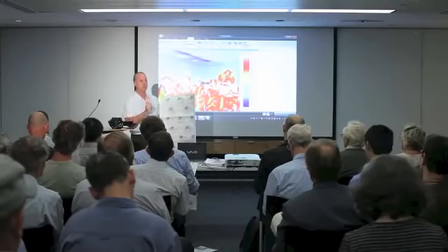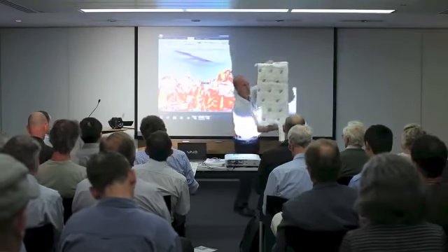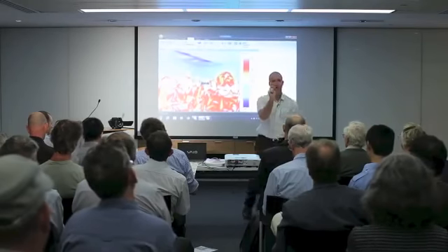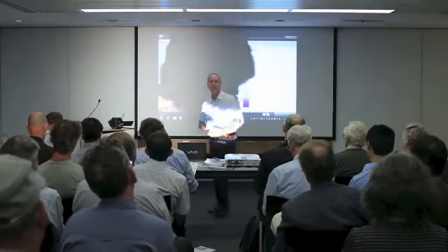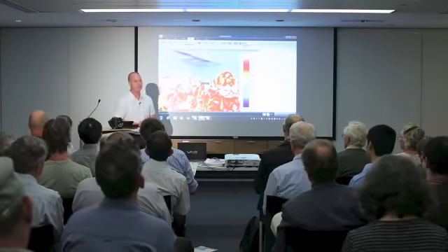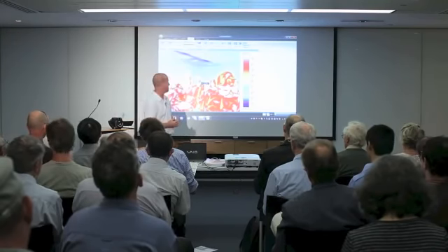Concrete's about 1 joule per gram of material. This material here is about 40 joules per gram across the melt range per degree. So every degree it goes up, it absorbs 40 joules. Concrete, every degree it goes up, it absorbs 1 joule per gram. Water is about 2 joules per gram when it's water. When it's ice, it's about 400 joules per gram across a very tight band. Water is one of the best phase change materials you'll ever find. The problem is it freezes at 0. And we're not Eskimos, okay? We don't want to live in that comfort band. So this is effectively room temperature ice.